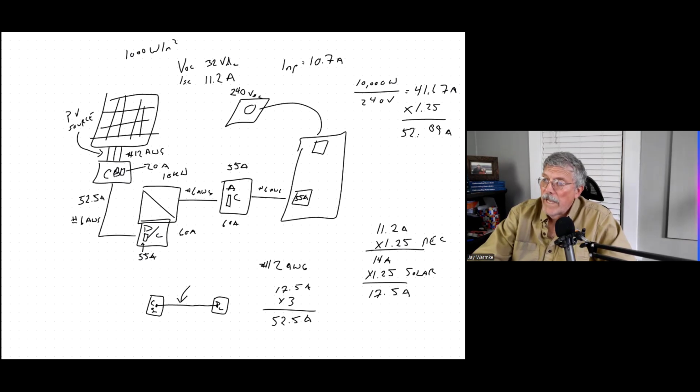The reason for that is what's referred to as the 120% rule. The 120% rule basically means that this circuit breaker panel box has an ampacity rating. Let's say that it's rated for 200 amps, and we have 200 amp service coming in from the utility.